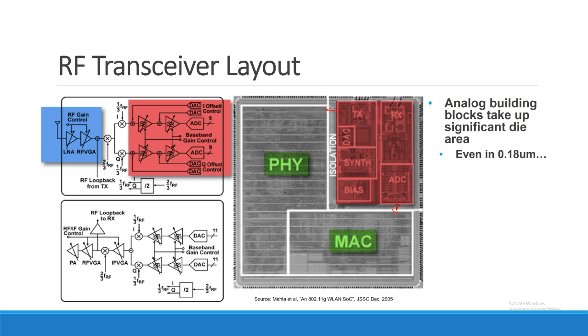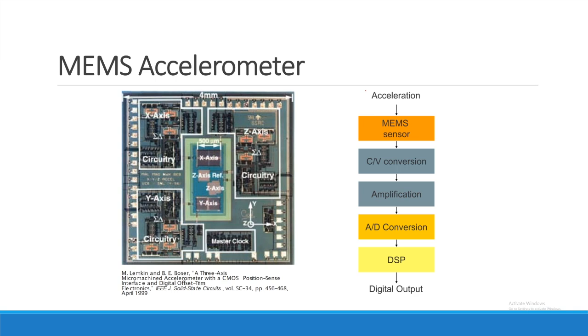Basically, you're worried about some digital, I'll be mean since I'm also a digital guy, some digital junk happening there, right? That digital junk can create noise, or really interference, that couples into the analog stuff. So as we'll maybe talk about a little more later on, one of the simplest ways to avoid that is just to leave space between them, okay? So a lot of these analog issues, even if you're sitting just next to some digital thing, turn out to be a pretty critical thing that you really have to worry about. So this is just another typical example of where analog really comes into the picture.